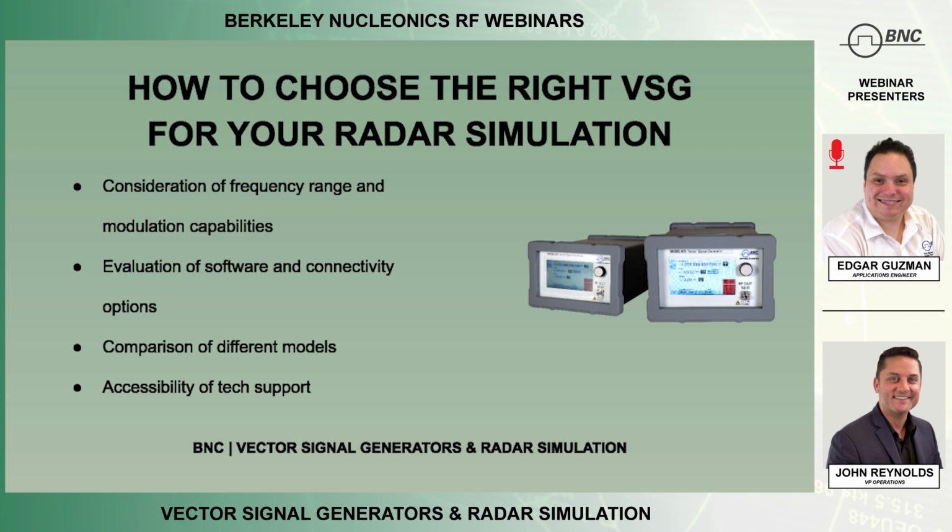Even within just standard signal generators, or RF signal generators, phase noise is a very important specification that a lot of people look at. The power levels you're able to get, and the actual accuracy of those power levels. So when you set it to 10 or 0 dBm, it's actually set to around that within the accuracy of the unit itself. So these are a lot of the specifications that you normally would talk to us about, and we help you choose the right VSG for your application.